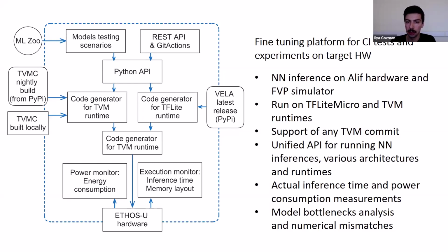Recompile automatically based on timer, component toolchain updates, and repository commits. Utilize hardware from Alif with Cortex-M55 and Ethos-U55 NPU SoC, as well as the ARM Corstone-300 simulator. Catalog results for change tracking.